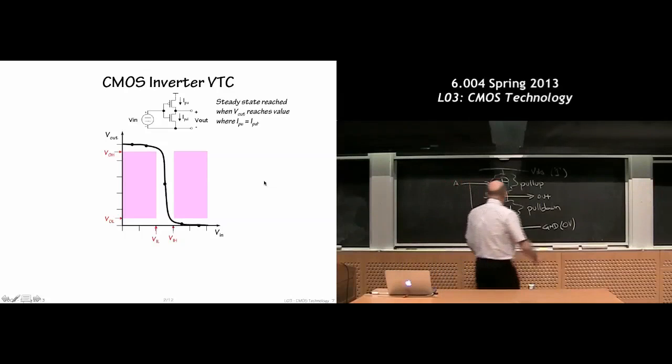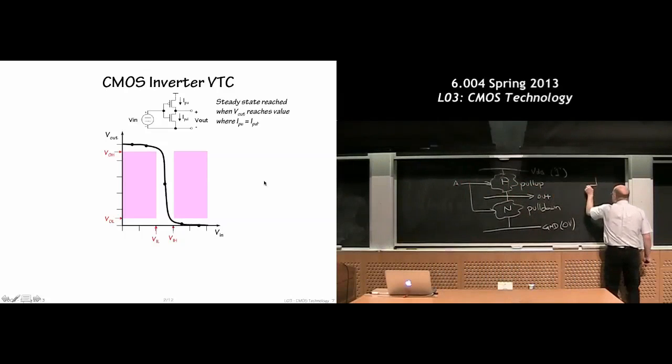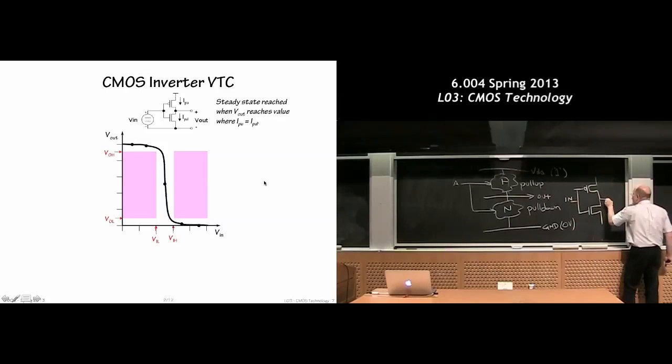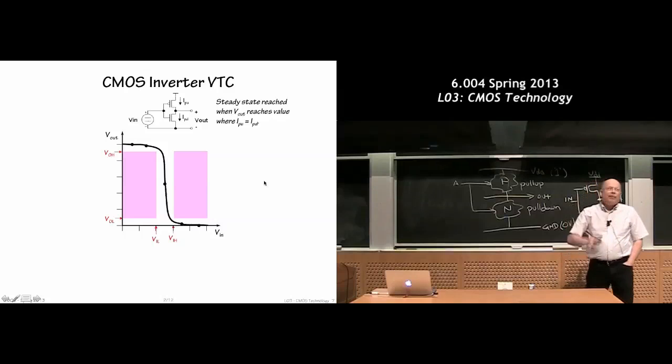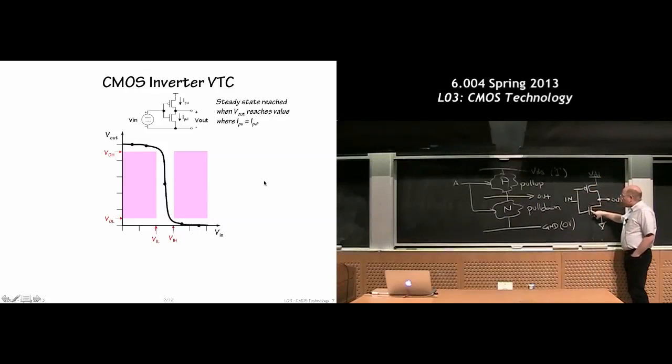Okay, so what's the simplest sort of network I can imagine here? I'm going to put in one P-channel device and one N-channel device, like so. So here's my input node here. Here's my output node. Here's VDD. Here's my ground connection. So let's build that device. First of all, notice the schematic symbols. This is an NFET. And this, the same picture, except with a little bubble on the input to remind us that it's inverting. In almost all logic diagrams, those little bubbles mean invert. So this means that this switch is conducting when the voltage is high. This switch is conducting when the gate voltage is low.